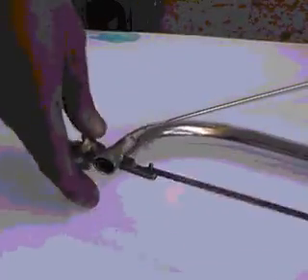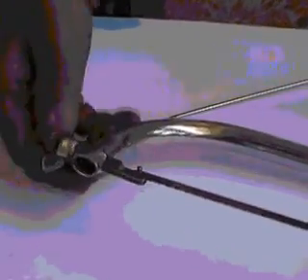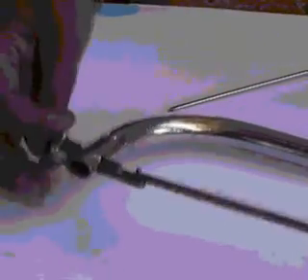To replace the blade, firstly loosen the fly nut. Open the fly nut to make it loose. We are opening the fly nut right now. Now we have opened the fly nut. Then the blade becomes free. Remove the blade and replace it. Again, tighten the fly nut.